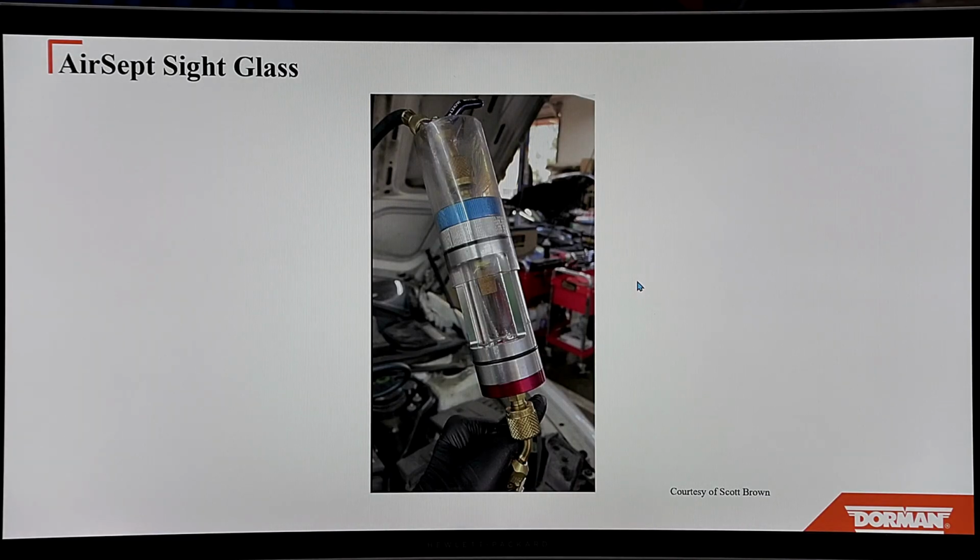Now, this little tool is phenomenal. You've seen in our webinars before, I've used this. You got a question about the AC compressor. Is it really working? Well, maybe it is, but watch this little video. Here's our high side, and here's our low side. First of all, we can see if oil comes in. How much? Is there a dye in the system? Take a look.